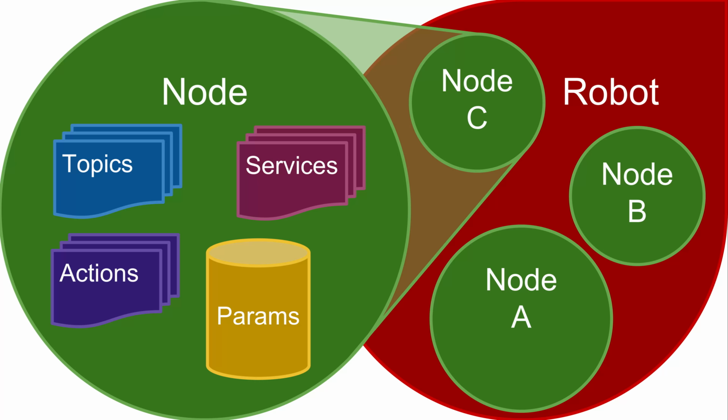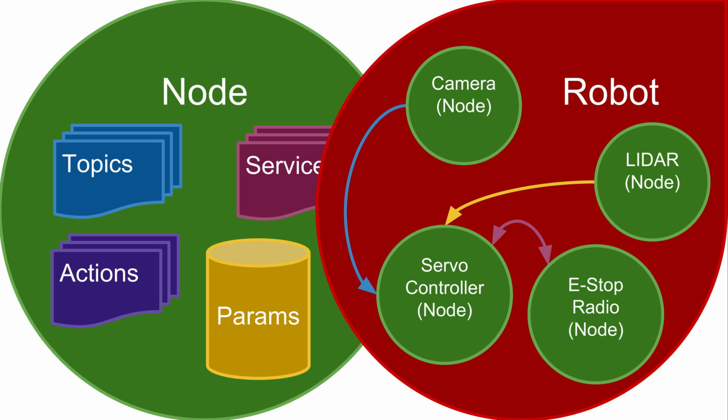We consider robotic middlewares, like ROS, where object types such as topics, services, parameters, etc. are organized under a namespace hierarchy. Subjects, depicted as nodes, representing servos, cameras, lidars, etc., intercommunicate within a peer-to-peer computation graph via standardized object APIs.